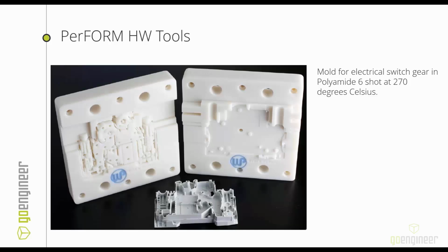If you're to go through a service bureau to have them make that for you because you don't have the technology in-house, just figure on them factoring that up by several times, where you'd be looking at $1,000 or more to have a set of tooling like that made. And again, it's geometry dependent, and company dependent on who you're going to be working with.